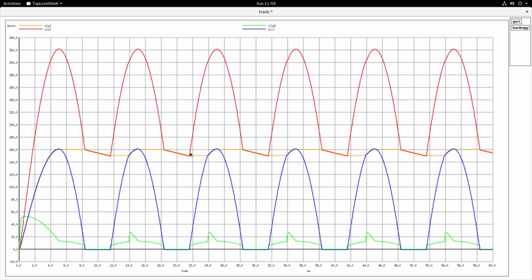This is generally not a problem, because the output of this is generally given to DC-DC converters or DC-AC inverters, and they have very good closed loop control mechanisms which will handle fluctuations in the DC link as provided by this power factor improvement circuit. So this fluctuation, this very high ripple, is generally not a problem, but that is a disadvantage of this particular circuit.